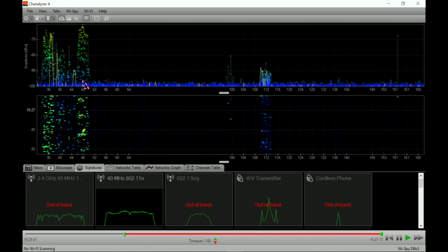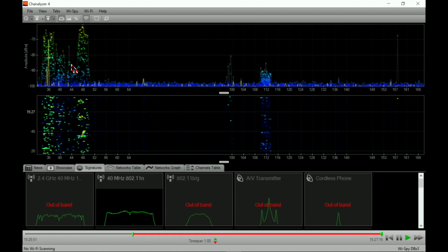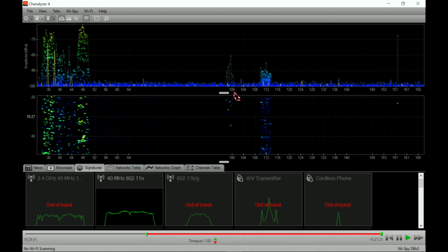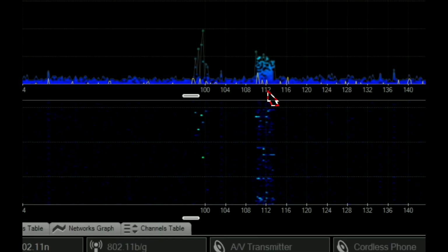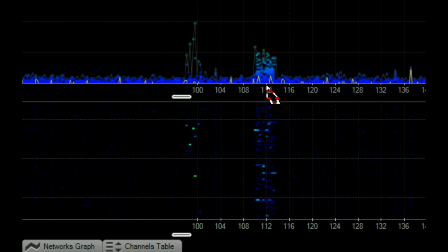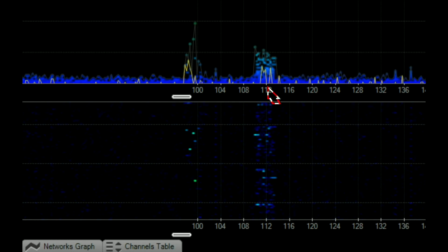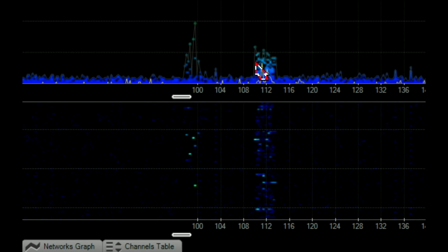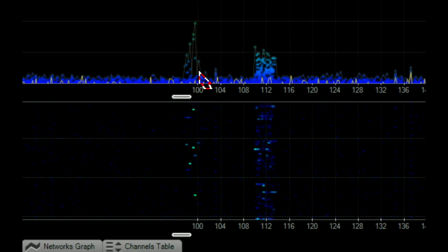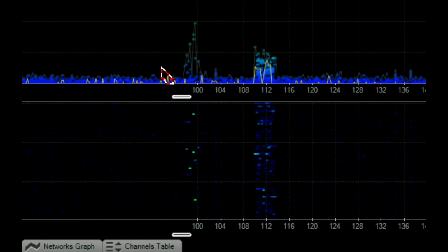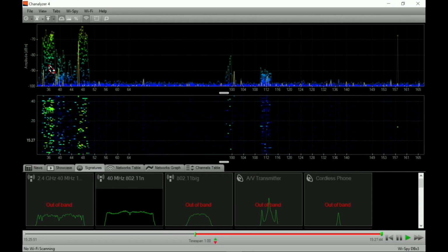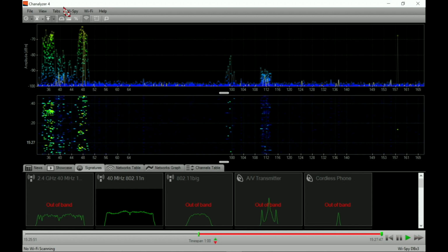So here you see again that obviously in this building there's some activity in channel 100, channel 112. We can later on try to look at this with Wireshark. Just looking at the shape, it looks to me like a frame-based transmission. You cannot say this with this device. This device is just showing you the shapes on layer 1. But you can still zoom in.